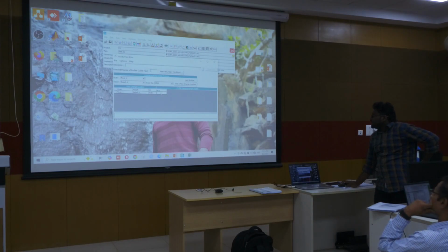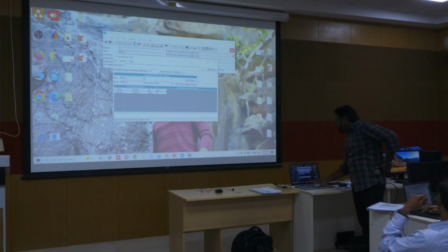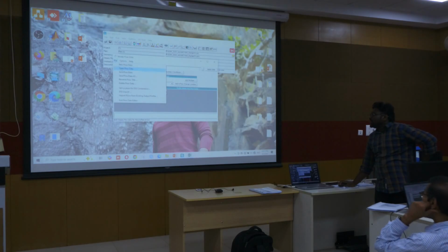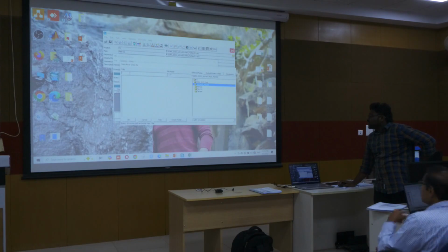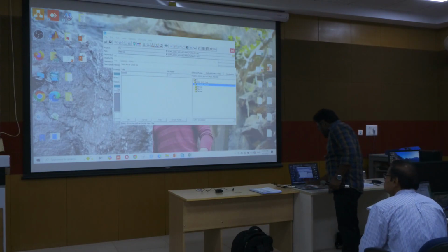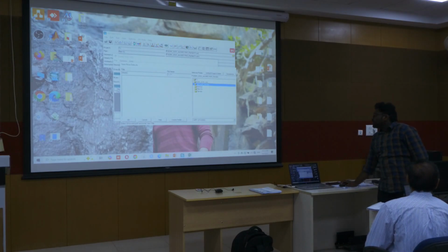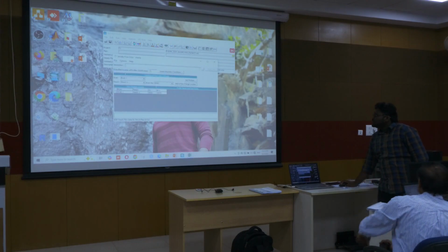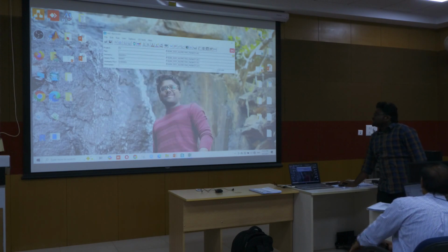Here you directly give the flow value. For example, you want to check at 20,000 meter cube per second. Just type that, 20,000, and save the steady flow data. Just click on file, save it, make it as steady. I am giving steady flow. Click OK. Go to file, save the data. Okay, then close this.